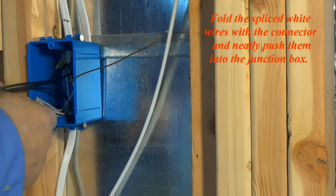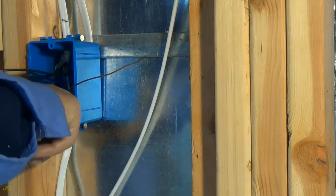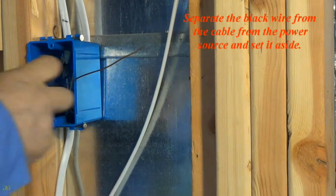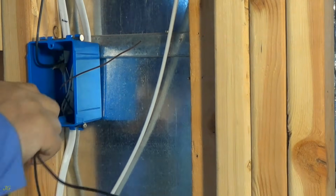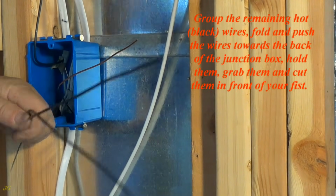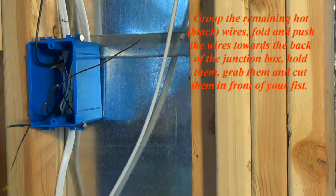Fold the spliced white wires with the connector and neatly push them into the junction box. Separate the black wire from the cable from the power source and set it aside. Group the remaining hot, black, wires. Fold and push the wires towards the back of the junction box.